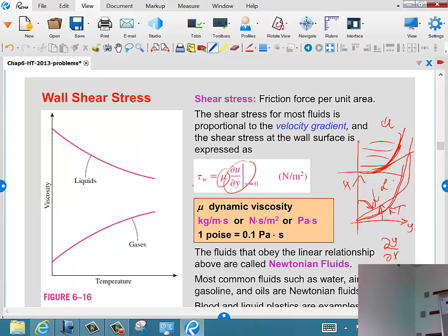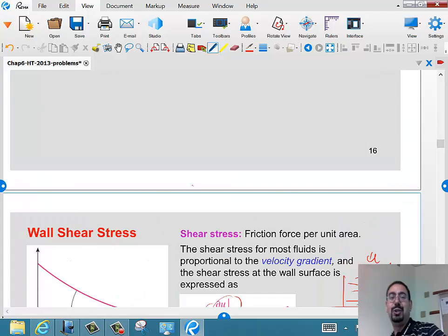So that's why turbulent is great for heat transfer, but from a fluid mechanics point of view, from a shear stress point of view, it's bad because it will increase the shear. Right? So when they have a submarine, they can actually make it move much faster if only they can make the flow around the submarine laminar. Actually my office mate, his PhD was about how we can make the flow on a submarine laminar all the way. Of course, that's really hard because the submarine is very long, right?